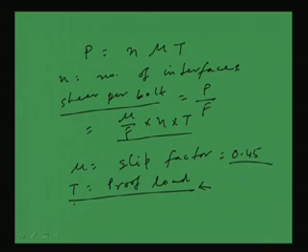For say a 22 mm diameter bolt, the strength given by the code is called the proof load, that is T. So from these formulas we can find the number of bolts required to carry a particular amount of load. This will be clear if we go through one example.